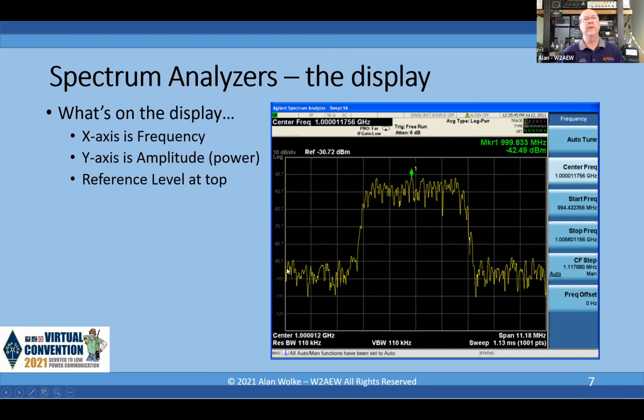Because as you might imagine, if the attenuator is set to 20 dB instead of 10 dB, the instrument's noise floor that shows up down here is going to be shown 10 dB higher, because the instrument is just going to say, okay, you've put 20 dB of attenuation in front of me. That means any signal that I'm going to show you is actually 20 dB higher, so I'm going to add 20 dB to all these numbers. By doing that, now your noise floor is 20 dB higher, because we've essentially artificially added that number so that everything else is accurate. So you want to properly set the reference level so that the attenuator gets optimally low enough to give you the best signal to noise ratio.